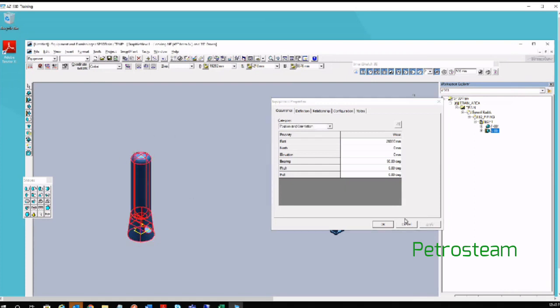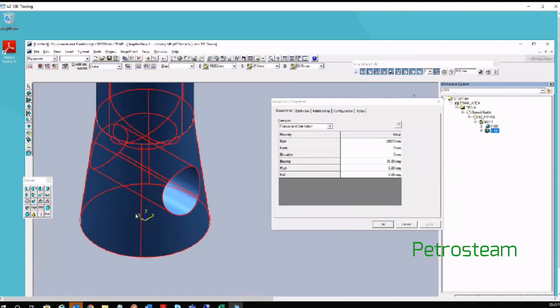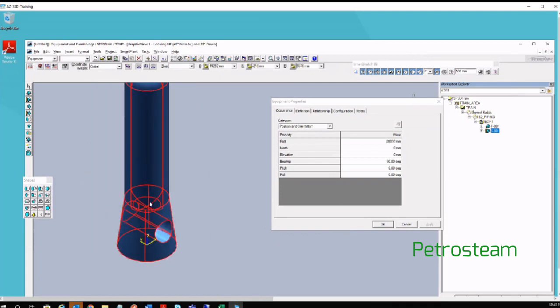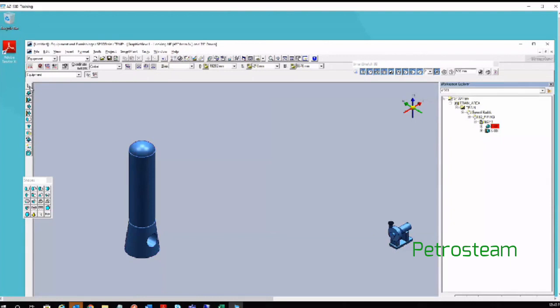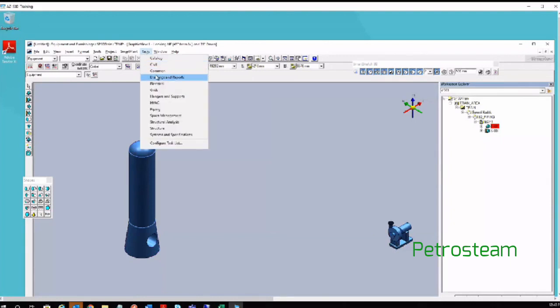As I told you, when you placed this V001 equipment definition, you selected this position, and from there you go on building the equipment. For every equipment there will be a reference position available. Make sure that reference position is exactly at the required place. Normally, this reference position is not visible when you are in a different task.